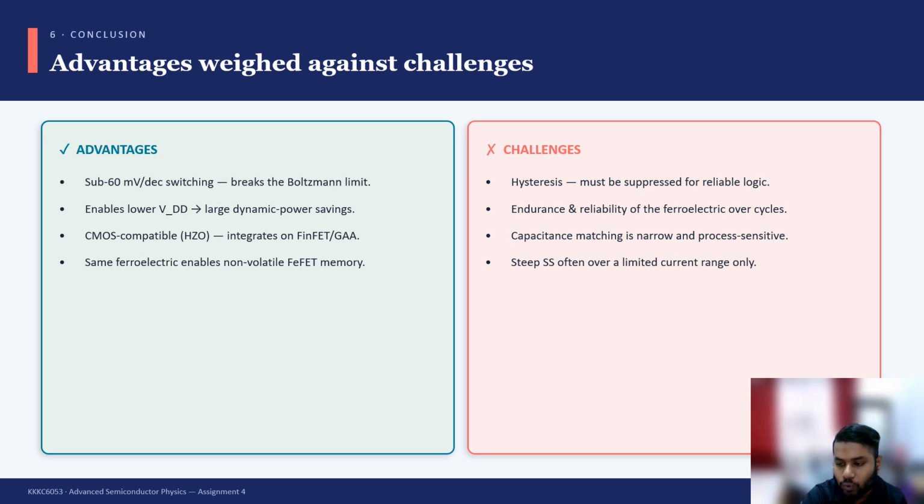On the challenge side, which I won't gloss over: hysteresis must be suppressed for clean logic operation. The long-term endurance and reliability of the ferroelectrics are still being proven. The capacitance matching window is narrow and sensitive to process variation, and as noted, the steep swing is frequently limited to a portion of the current range. These are engineering challenges, not fundamental roadblocks, and that distinction is what makes the device so promising.